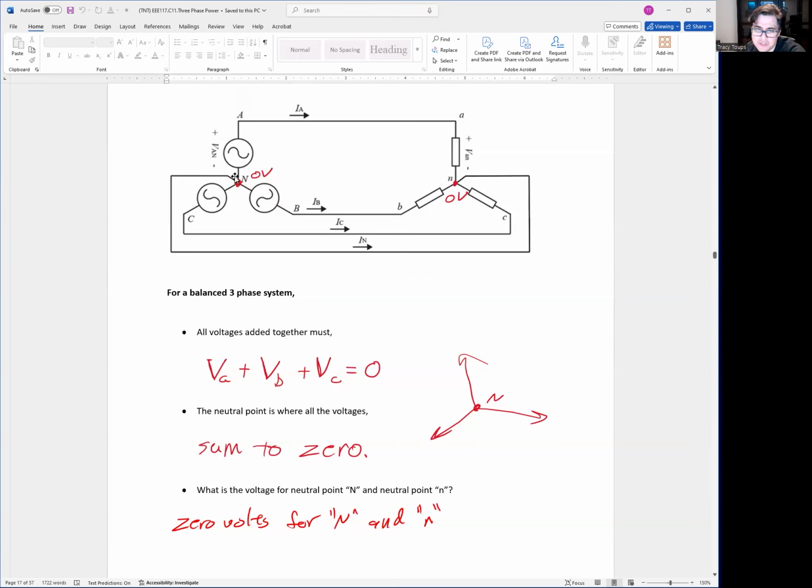Okay, but just to note that there is a neutral wire typically in place, especially in industrial settings where you might have, because one of these might be 3 separate lights or 3 separate rooms. You could turn one off, so because it's unbalanced, you're going to have to have a path for the current to flow whenever you turn some of your loads on and off. Okay.